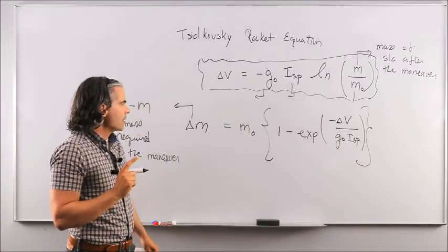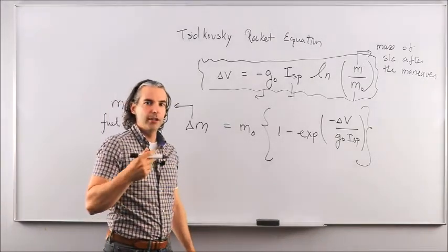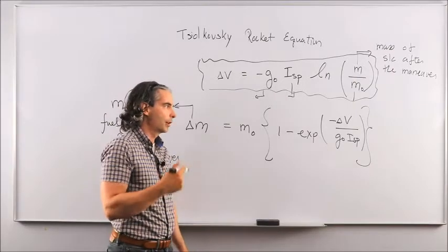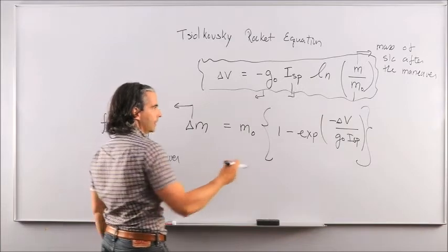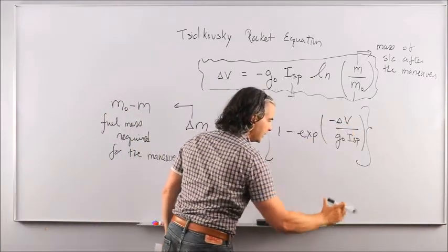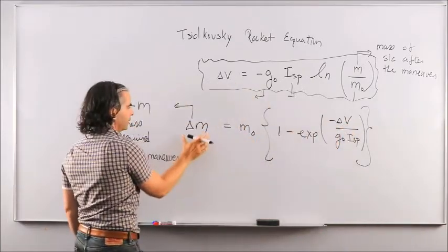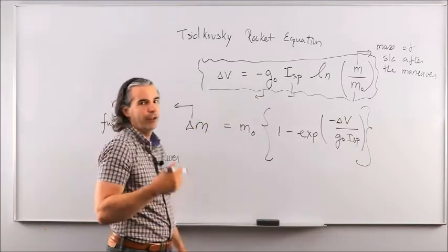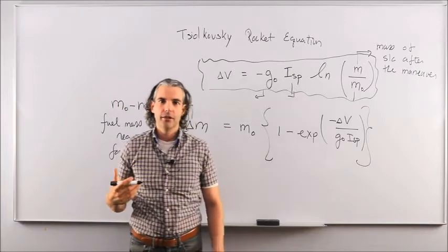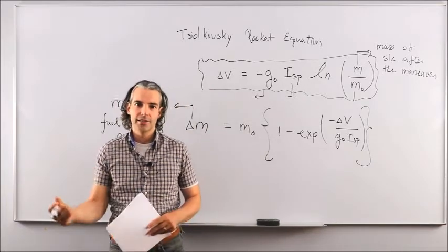Now, one spacecraft mission typically involves quite a bit more than one orbital maneuver. So what in practice people do is that they calculate the individual delta V's and then the individual delta m's, and then sum up all the delta m to come up with the final fuel budget of the entire spacecraft mission and size the engine accordingly.